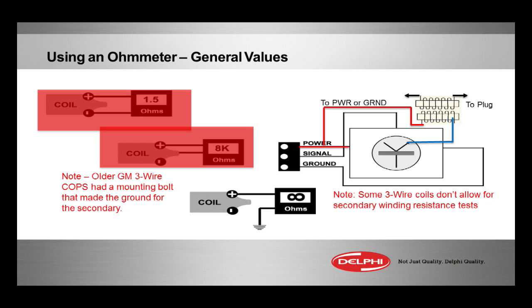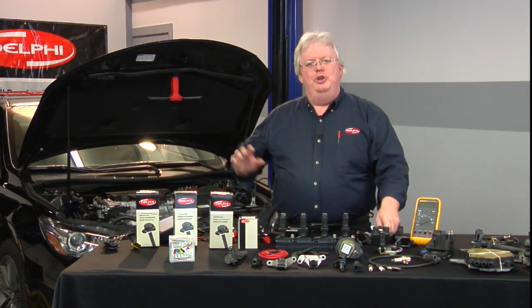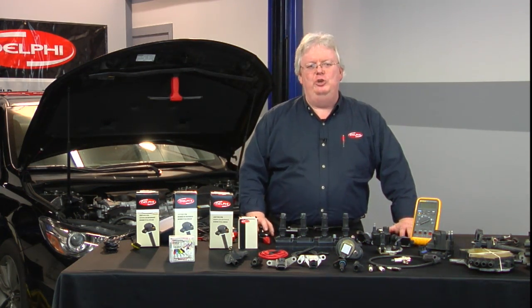Sometimes you couldn't. So it all varied. So again, I'll make the point really clear. You got more than 2 wires on a Coil-On-Plug, you're doing your testing exclusively on the car and no longer any resistance testing you can rely on.